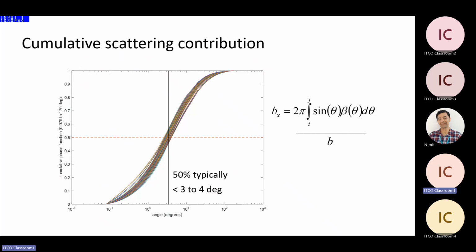But you would calibrate it, and then you would hose clamp it into a cage to take a vertical profile, and you get really crazy values. You wouldn't get consistent values. And then you put it back on the bench top, and it would be working again, exactly how you expected. We figured out that was because when you were hose clamping it into the cage, you were actually changing the alignment just a little bit.